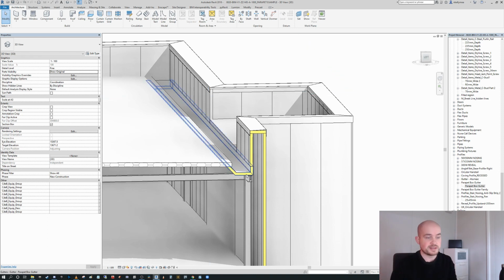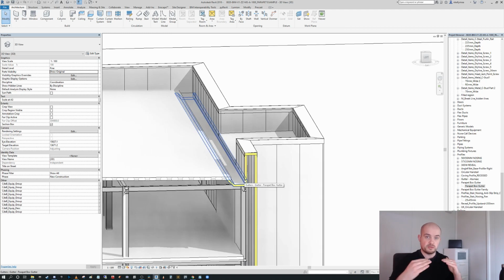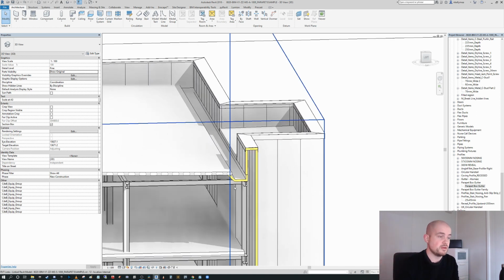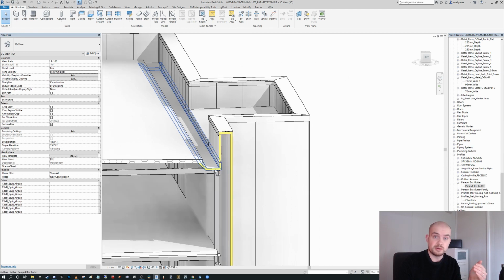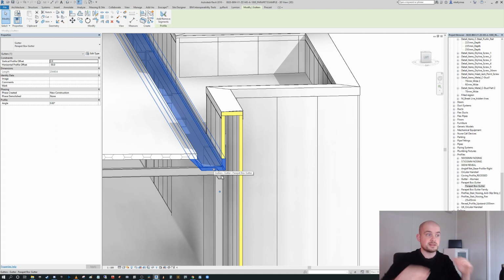So this is obviously flat, and what we'd really have, in intervals going down through the roof, depending on what the rain flow calculations would tell us, is a series of outlets going down the roof. In this instance, we do not know what those outlet intervals are, but also we can't introduce the falls to those outlets because it's just a profile down a path, right?